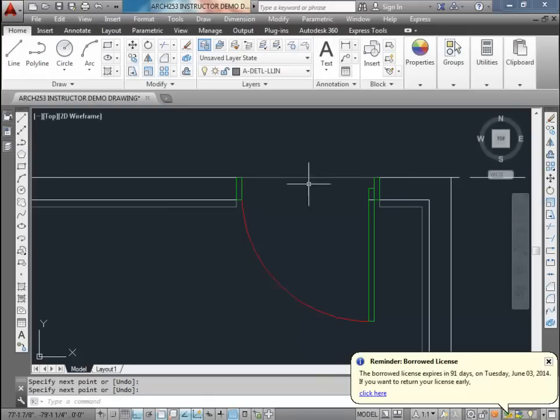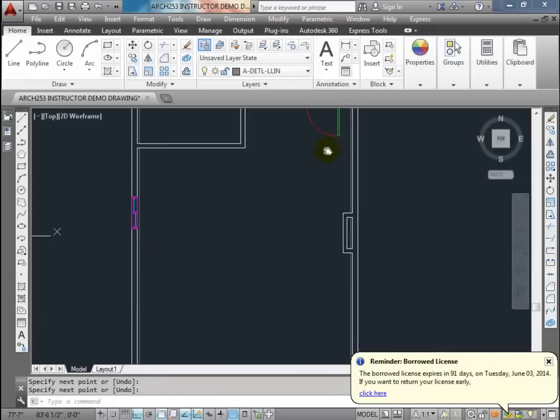So that door will actually break up the wall, but because there's a door buck, the foundation wall will also be broken up by that door as well. So now we can see that our opening, the slab, is actually going to come around the foundation wall, go to the back side of that door frame, and then come back in again and follow the lines of the foundation wall. That's going to be our door slab.